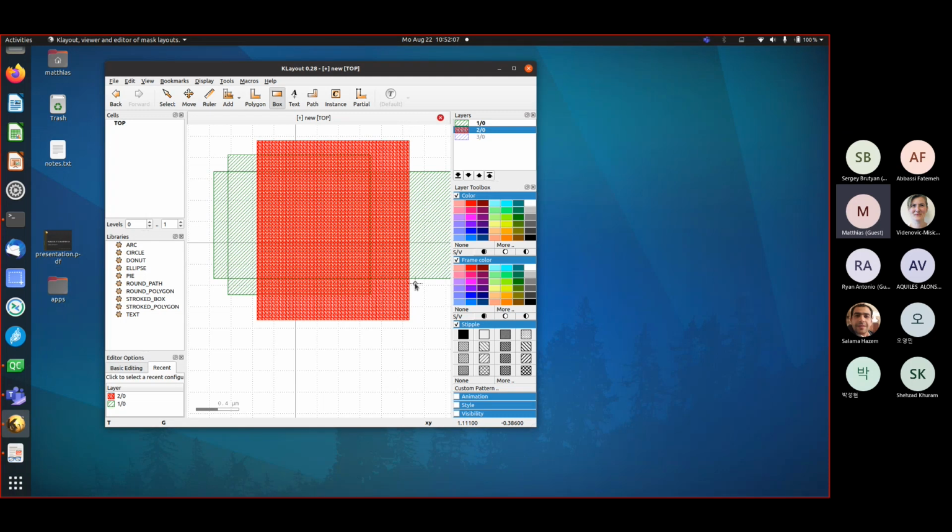But in Virtuoso, it's the text file, it's the display file, it's the layer mapping. All of that together is compiled into a PDK for Virtuoso, and someone else has done this work for you. And usually these people consider a lot of things like visibility of layers, how they overlay, what layers you typically overlay versus each other. So usually you're not concerned with this, and it's a kind of art to design such a setup properly.